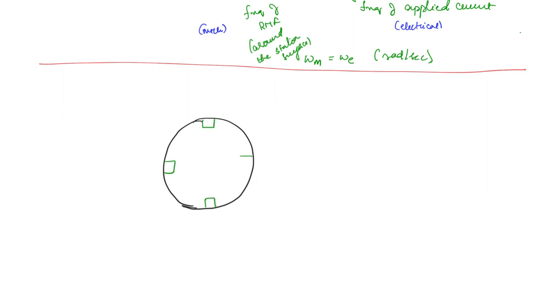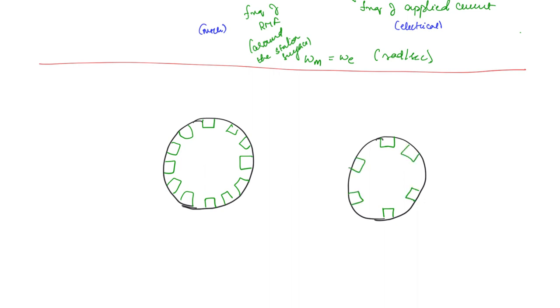So we can first draw the slots here. There will be 2 slots, so that the total number of slots we will have 12. Now how the windings should be placed so that we can get 2 poles, we can take the help of the single set. In the previous case we took something like this, right? So what were the coils here? This is A dash, B dash, C and C dash. So we got here A, after A we have C dash, B, A dash, C, B dash and then back to A. This was the cycle.